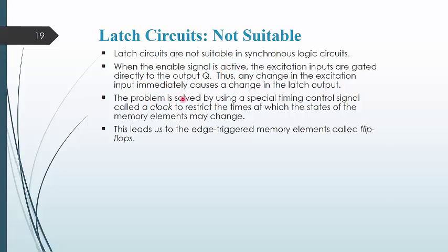This problem is solved in memory element circuitry by using a special timing control signal known as a clock. This clock restricts the times at which the states of the memory elements change, and because of this we are led towards edge-triggered memory elements, which are nothing but flip-flops. Up till now we have covered latches, which are level-triggered memory elements.